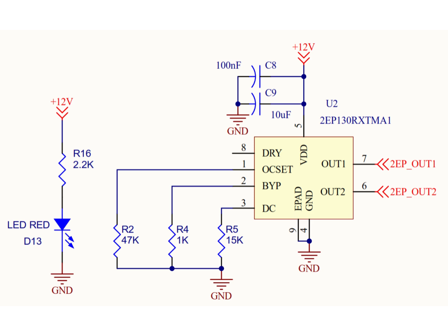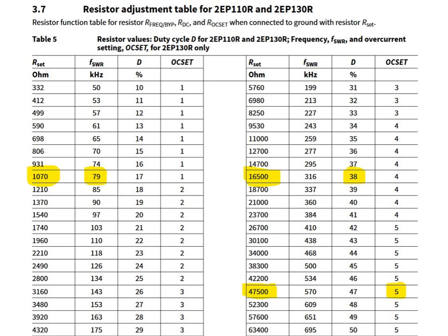By carefully controlling the duty cycle, we are able to generate asymmetric secondary voltages, resulting in the required +15 volt and -9 volt outputs after rectification and filtering. This technique avoids the need for separate converters and allows both gate drive voltages to be derived from a single isolated transformer.